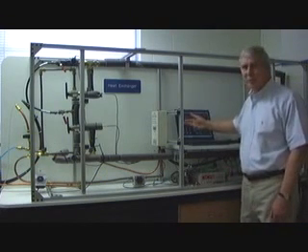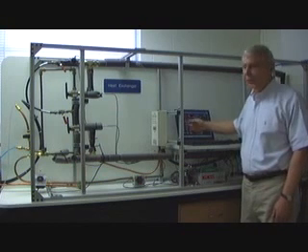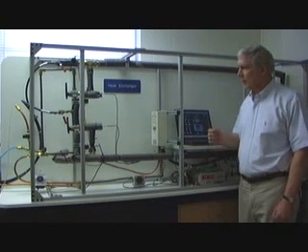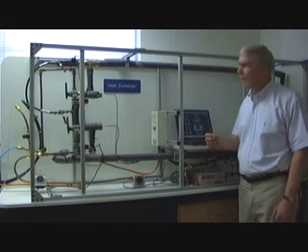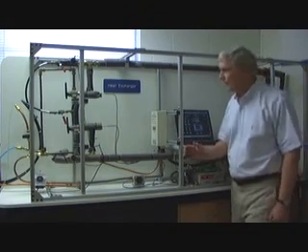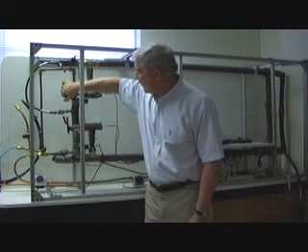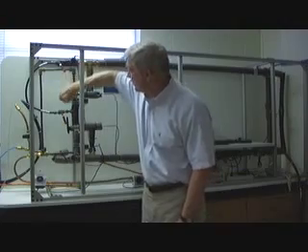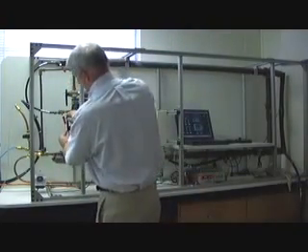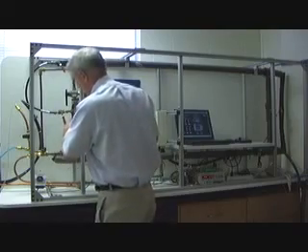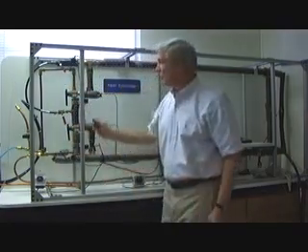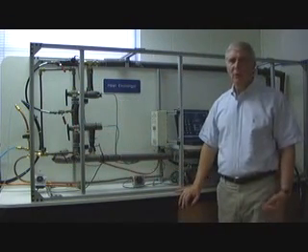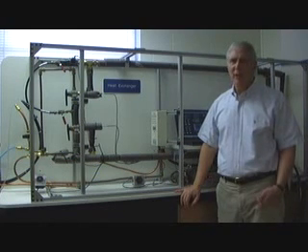You will collect temperature data at the inlet, the exit, and the midpoint, and you will collect flow rate. Do this for the various flow rates described in your lab write-up. When you're done with that configuration, come over here, change the flow configuration. In this case, parallel, I'm going to switch it to counterflow. The valves are kind of hard to turn. And reset the flow rates using the red-handled valves. Again, wait for the system to come to steady state. When it's reached steady state, record the temperatures and the flow rates again.